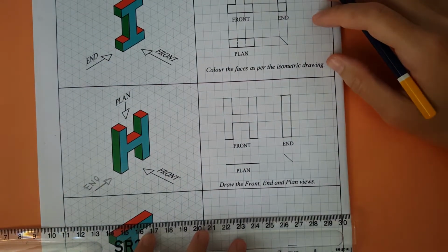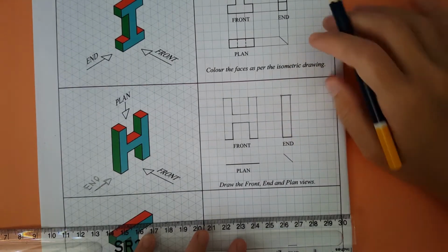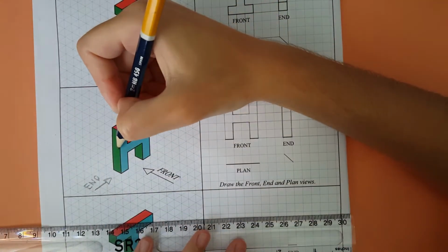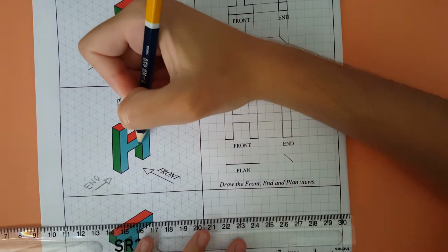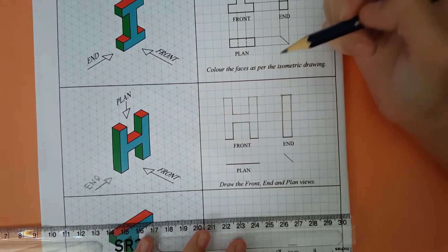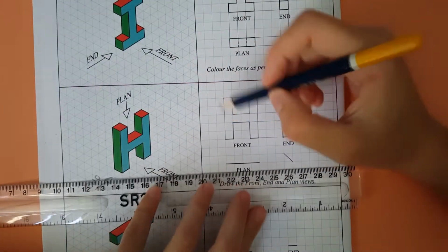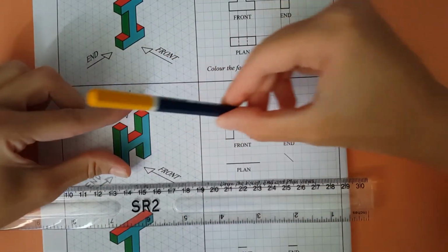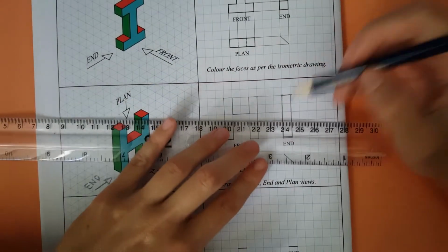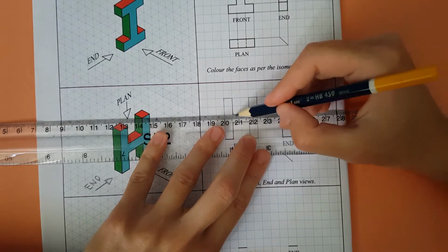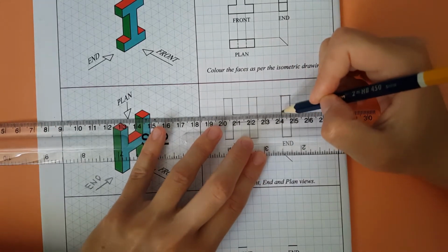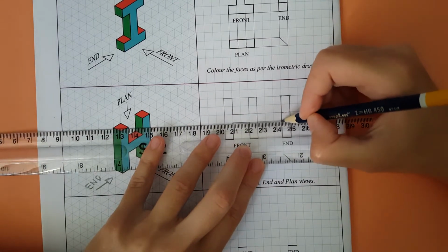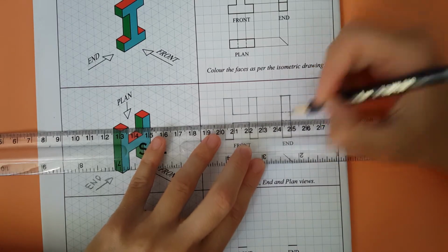Now the end seems finished, however it has some missing information in the middle. Even though I can't see those two lines in the middle right there, I still have to show them somehow on the end. This is so the end wouldn't look like it is showing a solid block, because it isn't after all. And we show those two lines by drawing hidden lines. And we draw hidden lines by drawing a broken line. Make sure that the two lines look equal to each other.